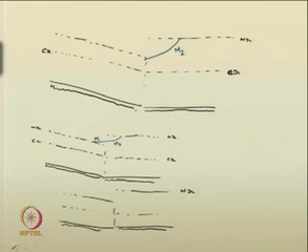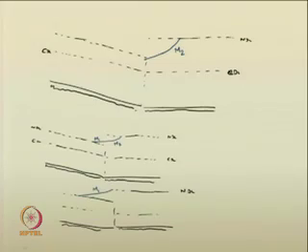The water surface will just start from here like this, and on reaching this junction it will be having a gradually varied flow M1 in channel 1 and reaches here, and in channel 2 the flow is entirely uniform, following the normal depth line like that. So, out of these three possible situations, which one do you think is correct, or which one is theoretically possible? Now, you look into these cases.